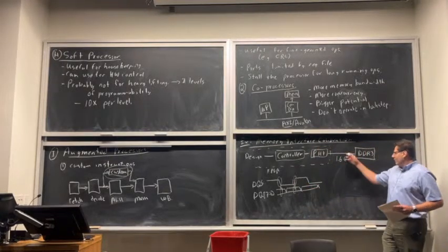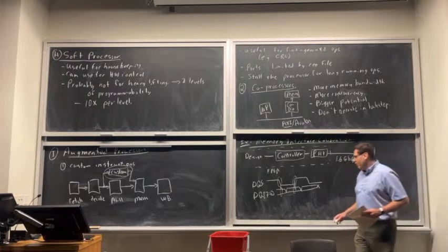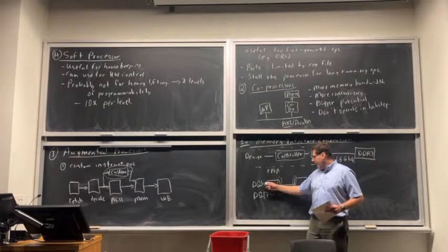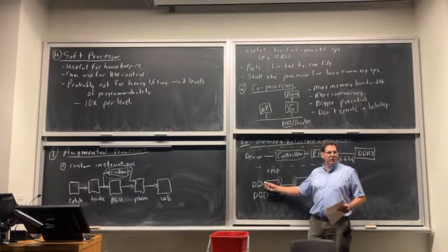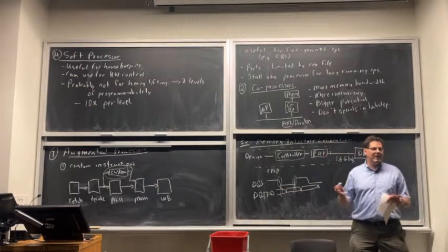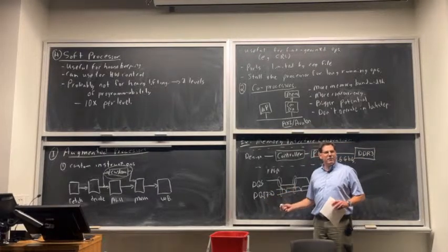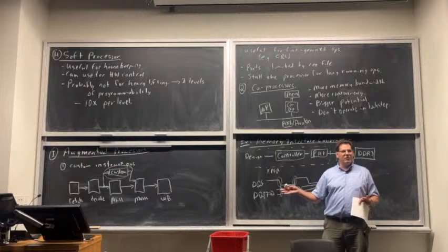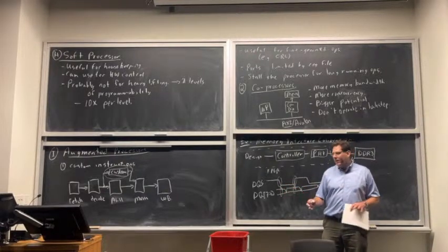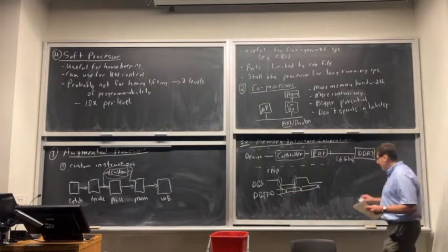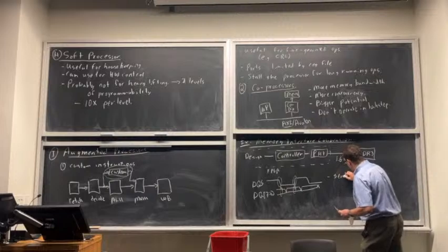I told you this was 64 bits wide. So you send multiple DQSs and multiple DQs. For every 8 bits of data, you send a different strobe. The reason you send different strobes is there's skew between this data. If you try to send one strobe for all 64 bits, it's not very reliable. At these speeds, there's just too much data skew. So you send one for every 8. Does that make sense? So we send a strobe to the memory.